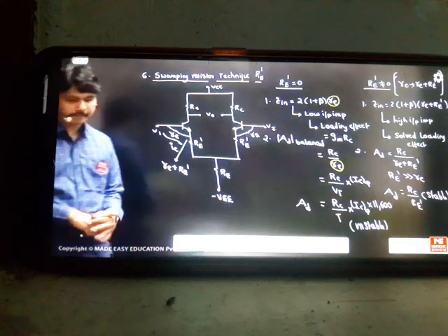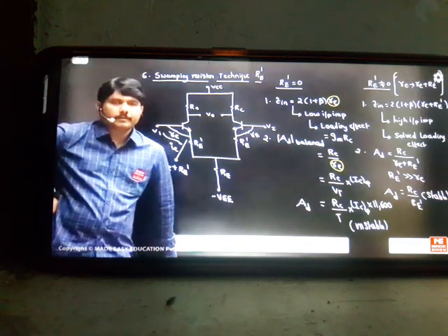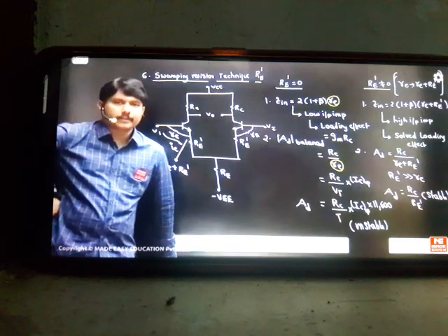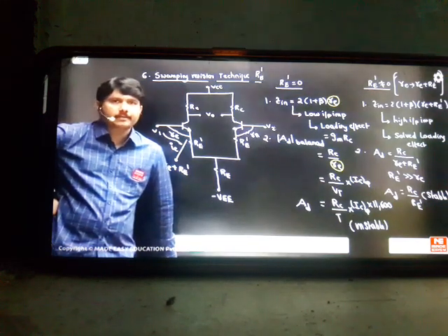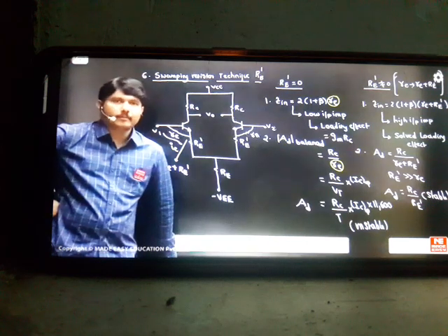See how the questions will be. Rahman, why is common mode rejected? The inputs for a differential amplifier are not common inputs. We give differential inputs because we made the circuit in such a manner. It's a symmetrical circuit. A symmetrical circuit never accepts common inputs. It will accept only differential inputs. That's why common mode became unwanted.